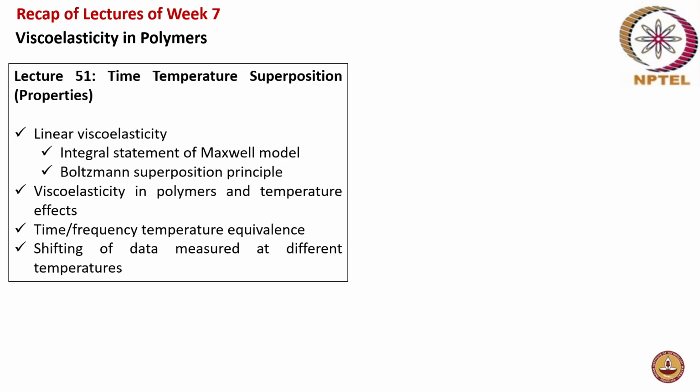The next lecture was on time temperature superposition. So the linear viscoelasticity, the integral statement for the Maxwell model, the Boltzmann superposition principle was discussed, and time, frequency, temperature equivalence. Shifting of data measured at different temperatures. So for a particular range of frequency, you can do it for different temperatures, and then you can make a master curve.